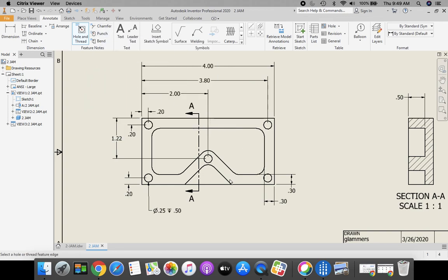We could do this angle dimension in here. So let's go back to our dimension tool. Click on your angle line. Click on your horizontal line. Okay, now you see how it puts the 45-degree on our block. So that's just the order that we selected in. So let's do our bottom line first and then our angle line, and see how that takes our 45 degrees and puts it on the outside now. Okay, that's a much better spot.